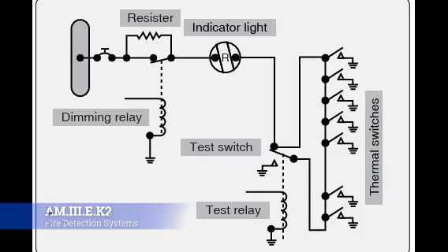If you need a refresher on how that works, essentially as it heats up, the resistance in a conductor drops down, and that allows the circuit to complete, and then it'll cause the light to illuminate up in the cockpit, allowing you to know that, hey, look, there is a fire on board.